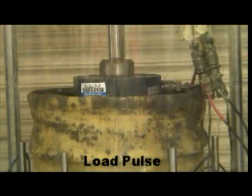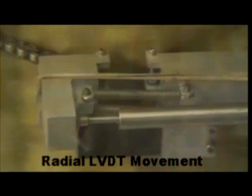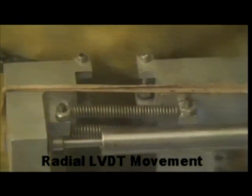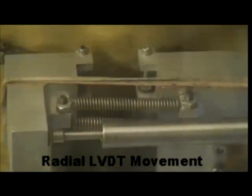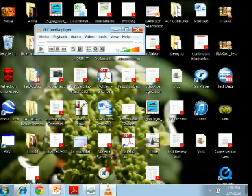One of Professor Tutumluer's students, Hai Huang, who is now a professor at one of the Penn State universities, was doing his PhD working on a lot of discrete element work. That is when some of those UP ballast box studies started, and they tried to achieve how to simulate the field conditions in the DEM. They correlated that to void ratio, measuring how much material goes in a given volume. They found the void ratio to be about 0.6. So when we constructed these specimens, the first idea was to keep the void ratio around the same.